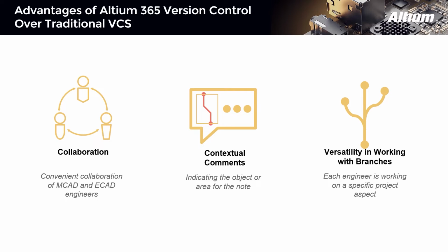Last but not least, it's an opportunity to work with branches. For example, there are two engineers working with the board separately from each other. Each of them performs their part of the work, and they can merge their changes into one file. This functionality is currently available for schematics, but merging for boards has limitations and is currently under active development. If you want to provide feedback on this functionality, feel free to reach out to me in an email, which I'll provide later in the questions section.